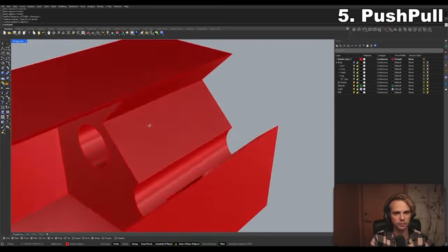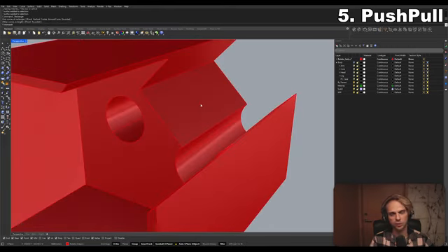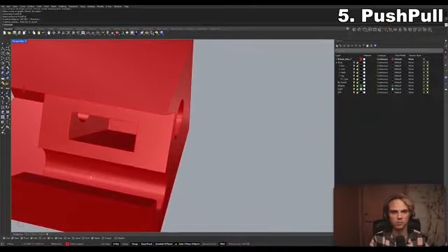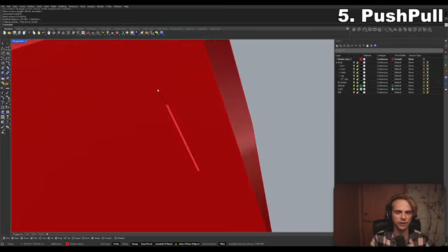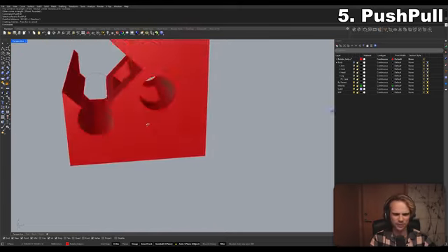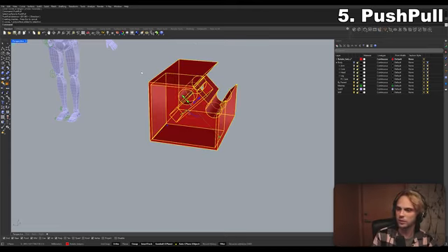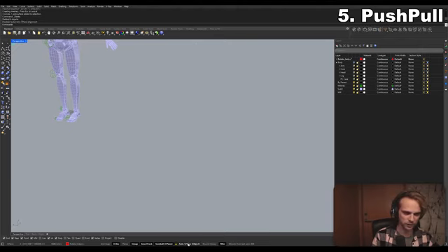Actually, I'm curious how will it behave if I were to, okay, we select this, so the C-plane becomes here, and I model out some sort of a rectangle real quick, or draw out a rectangle, push-pull again, select the surface inside, push it in until here, works like a charm, no issues whatsoever. I actually pushed it a little bit too close to the bottom, so now it's peeking out the Boolean difference carved into the bottom. Anyway, I guess you can see the possibilities of this tool, and yeah, this is such a welcome addition, a great tool to have. Moving on, let's reset, there we go.